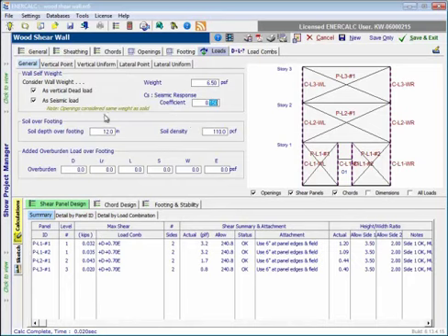Notice that in the wood shear wall module, openings are considered to be the same weight as the solid portions of the wall. The reason for that is basically as a simplification, because in wood framed construction of normal nominal dimensional lumber, the openings will commonly be filled with either a door of some construction, or a window of some sort of construction, or a louver, or there may be ductwork framing into it and providing some small amount of weight to